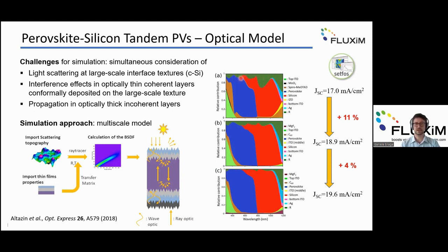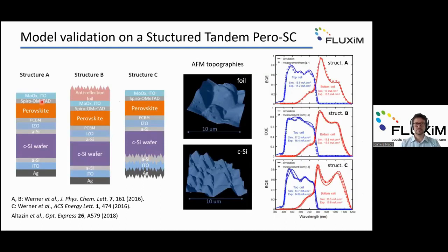So this green part of the EQE is giving you the total reflection of the solar cell. The JSC, because of this light reflection, is lower than the JSC of an optimized solar cell, in which the reflection is lower because I've been adding some structures, for example, as I said, in the anti-reflection coating. So the model and the experiments are fitting well.